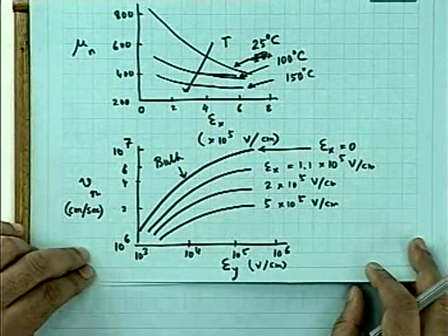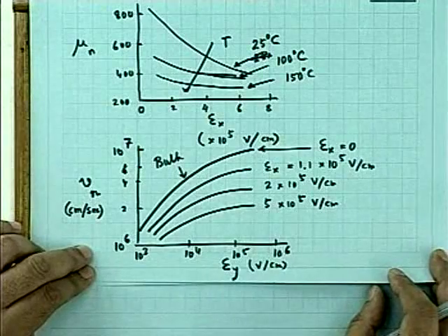The drain current expression in a MOSFET requires an accurate mobility model, and this mobility model is different from the normal mobility model because now the carriers experience not only a field along the direction of their motion but also perpendicular to the direction of the motion.